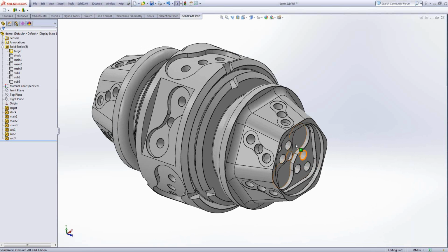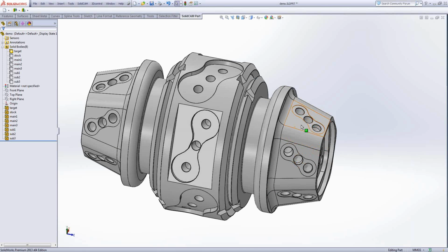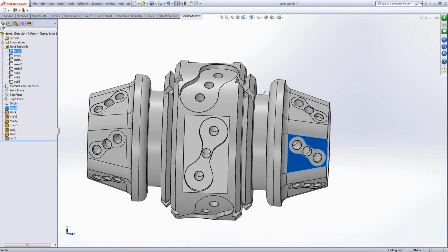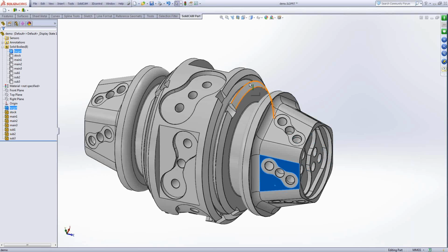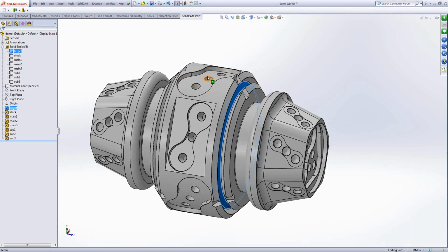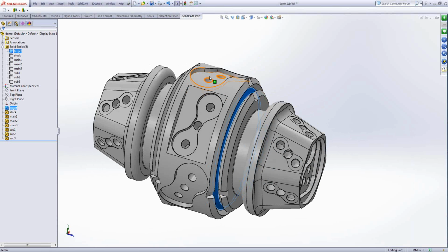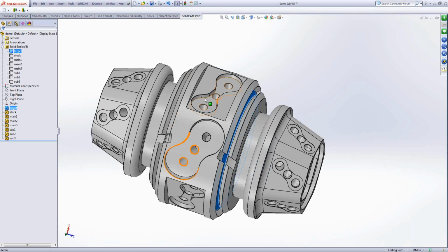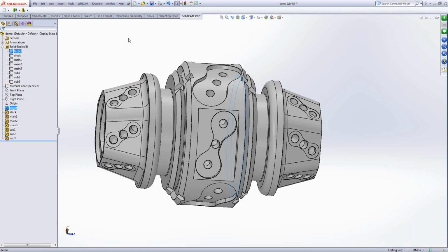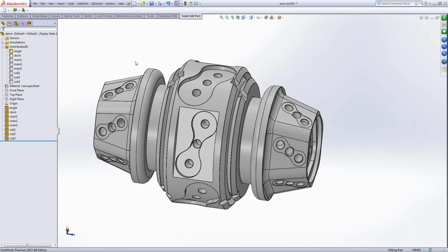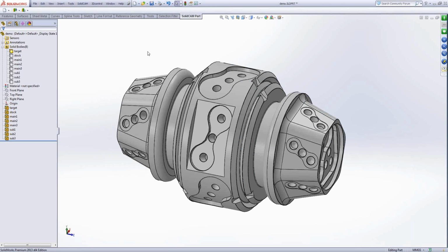I can work on angled faces, indexial. I can rotate and make transform. I can use this part for turning and grooving operations, angle grooving, radial operations, and radial drilling. I can demonstrate on this part almost everything in SolidCAM.